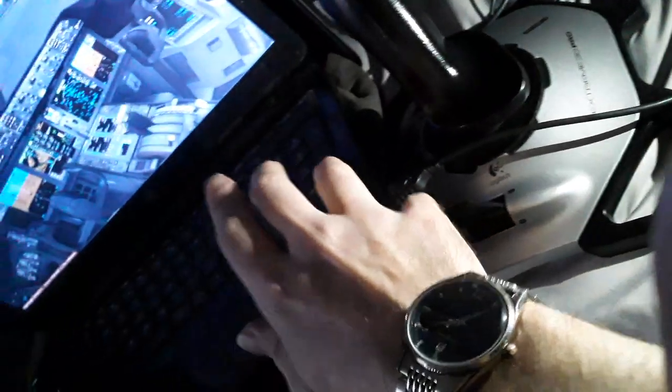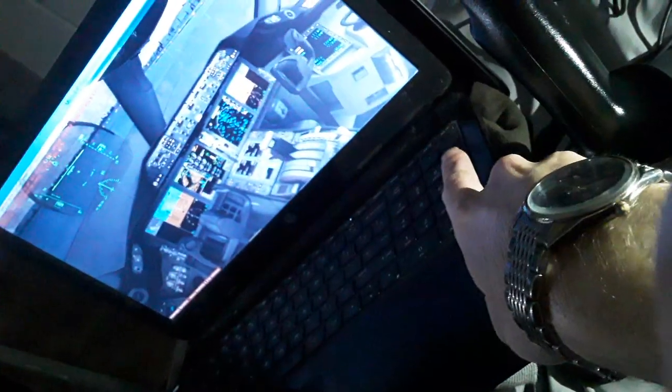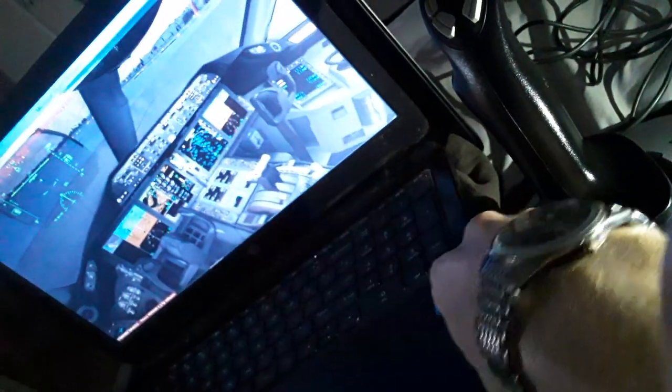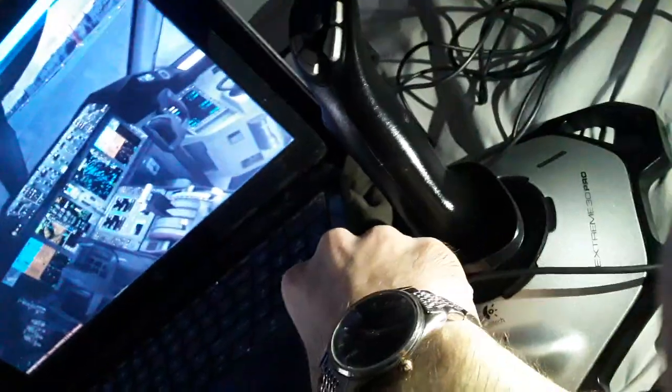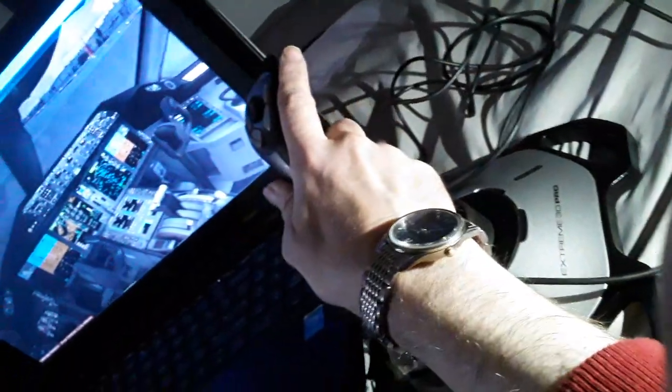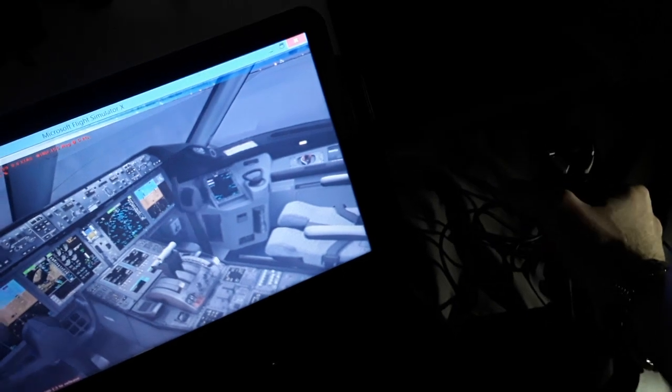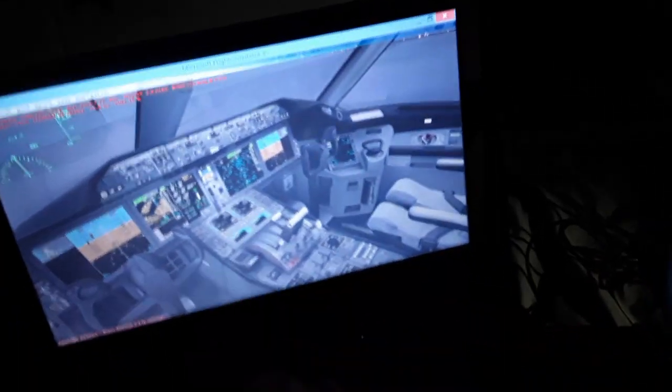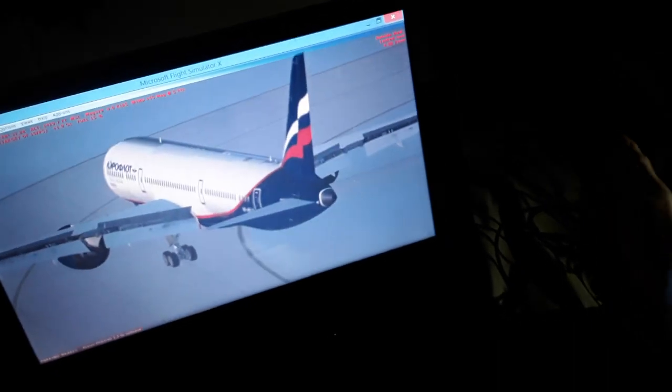Also you can see in the Airbus and the Boeing we have the thrust control over here, using this slider, so we can actuate the thrust control. You can see what percentage of engine thrust is produced over here when flying. So climb, descend, make turns to the right, make turns to the left. You can see the screens. Both controls are interconnected in the Boeing. The captain and the first officer, you need to apply some override force when flying to control either side. So in the Airbus you just have the side stick priority or dual input.